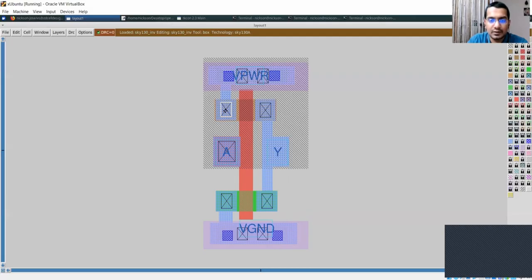Okay, so now we have a blanket tungsten layer over here, which is the contact holes. Now these contact holes have to be connected to a higher metal level, higher metal layer. So we use aluminum as a metal layer. We deposit an aluminum layer over here, and then we pattern this aluminum layer to take it to the top level. So we use again mask 13. Mask 13, the process again still remains the same. Mask 13 is used to block certain areas of the aluminum where you want to take out the contact holes right to the top, and the remaining areas of your aluminum are etched out. Okay, so this is how we do it.